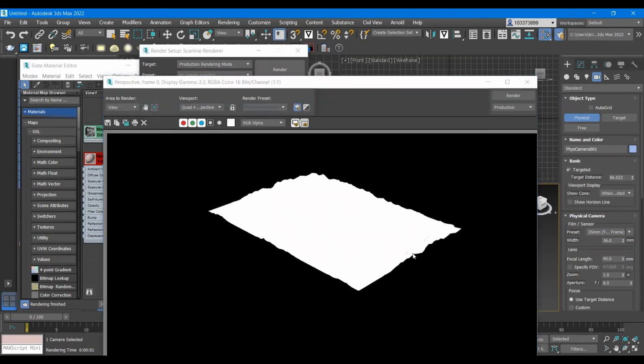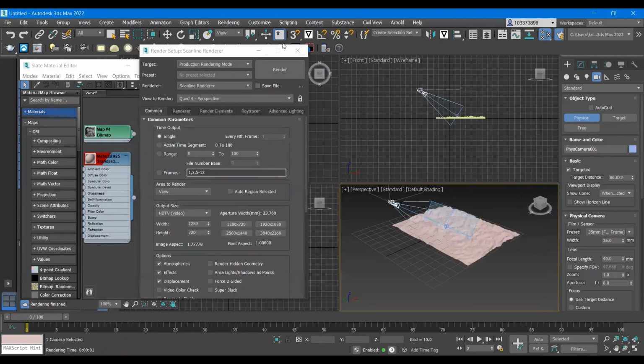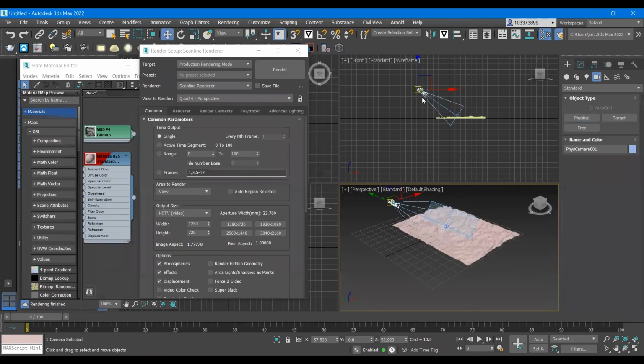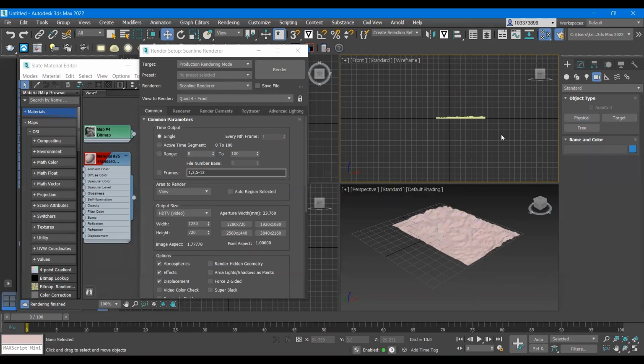As you see, you can see small contours and height on the plane. With the V-Ray option, you'll get a better render, showing some contours, some height, and you can also export it, or save it as a JPEG after you have finished rendering. And this is all from me, to show you how you can create contours in 3D Max using a height map. Thank you for watching.